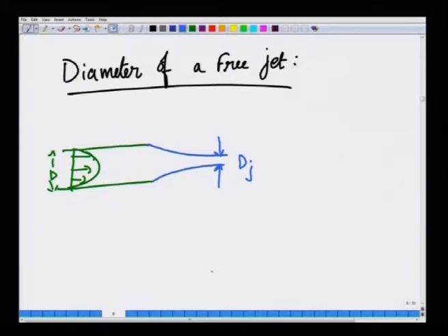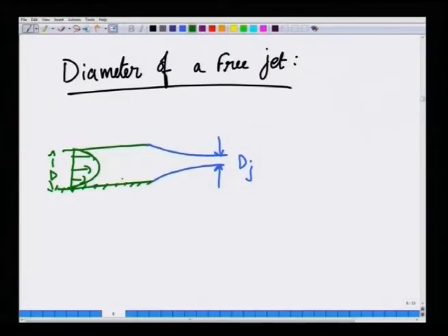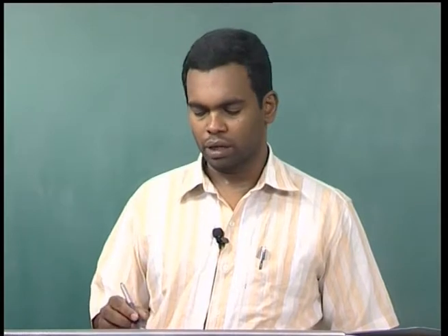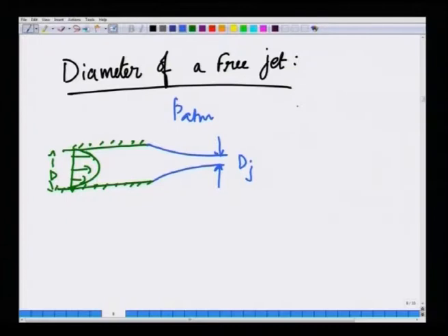That is because when the fluid is flowing within the tube, there are viscous shear stresses exerted on the surface of the tube that are exerted on the fluid, which drags the fluid, whereas once the fluid emerges into the atmosphere, so this is atmospheric pressure, there are no shear stresses that are acting, so the fluid tends to accelerate a little bit to reach the new steady state. But when it tries to do that, since there are lesser forces, let us first write down the mass balance.